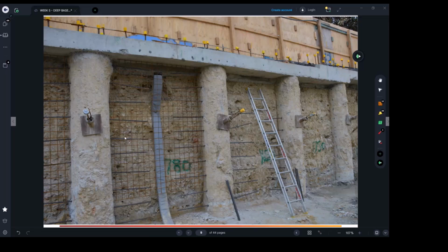Now in this project, it seems that their piles will not go 9 meters if it was one basement. It did not go for a decent double basement height embedment, because probably there was a lot of rock. So what they did, they only went 1 meter deep below the basement level to just anchor the bottom, and then they used a nail, which will support the pile at this level. So that's another process we do before thinking about placing the shotcrete wall.